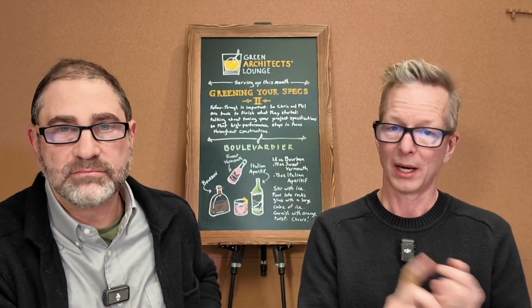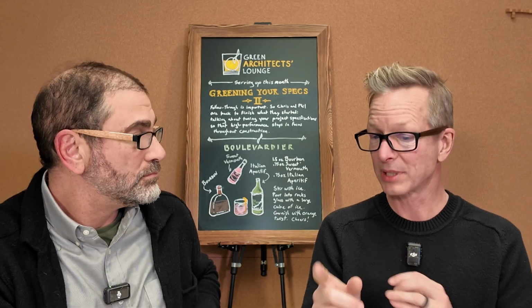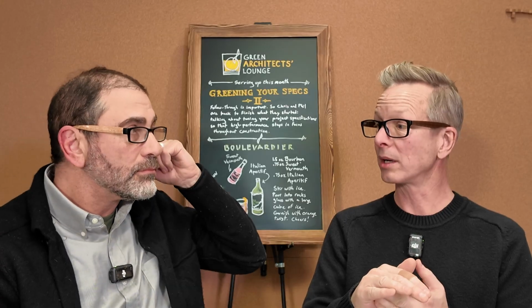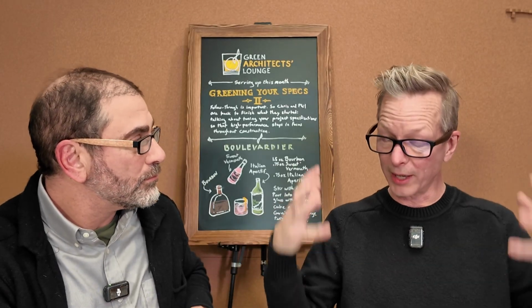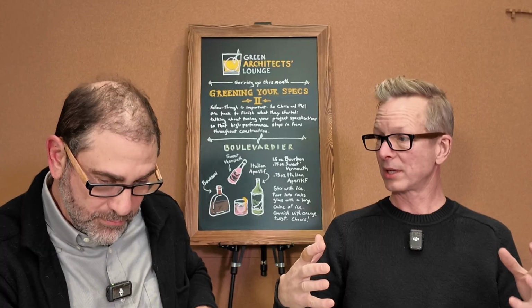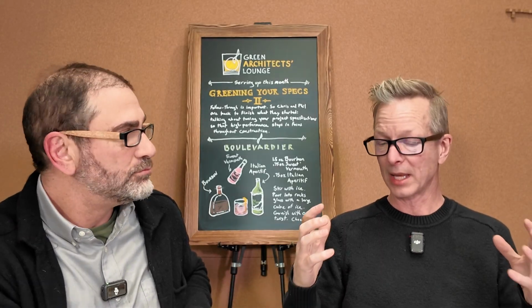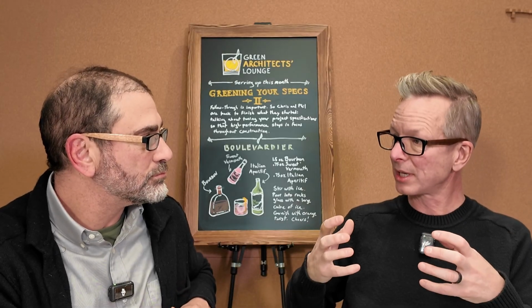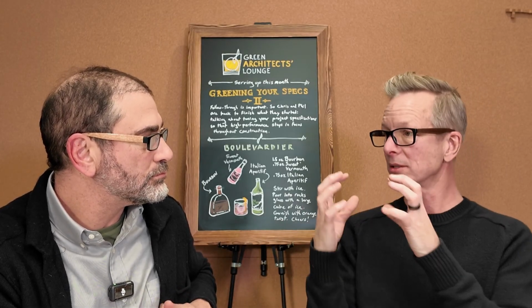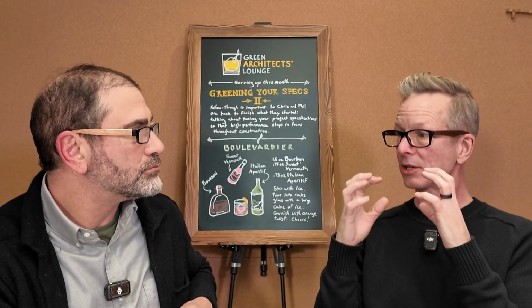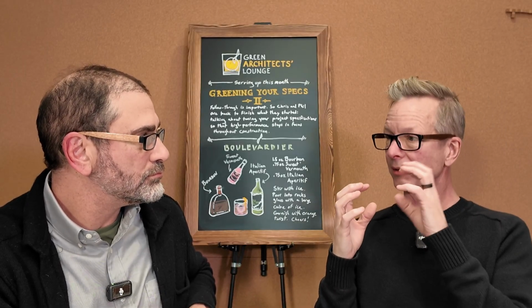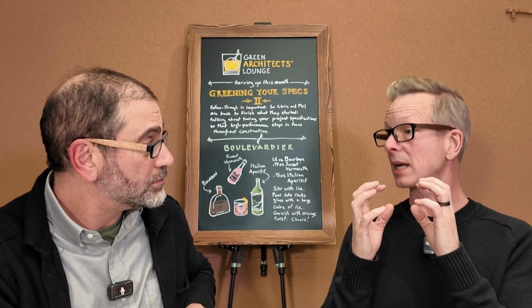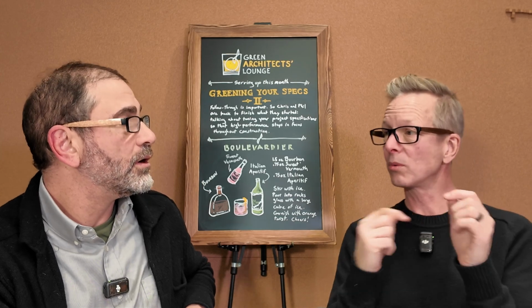Right, across the board. I will say, timestamp us, we're at December 10th. In February, Mitsubishi's coming out with their new line of air-to-water heat pumps. I was talking to Dana Fisher. It's very exciting. There's the traditional air-to-water heat pump pack on the outside, but it has the heat exchanger on the inside, so it's like a little sandwich. All your refrigerant is out here, and it comes into the wall just a little bit, and then your exchanger is inside. Right on the inside. So you don't have that whole issue, what happens with the water going in?